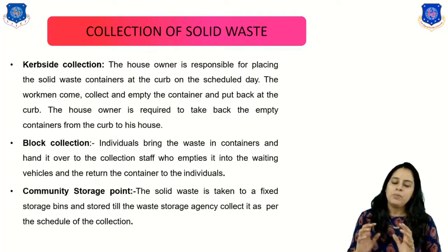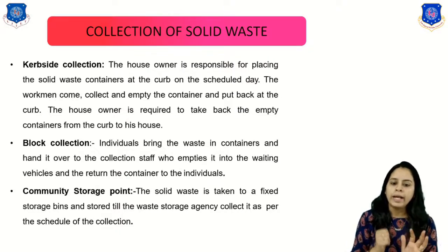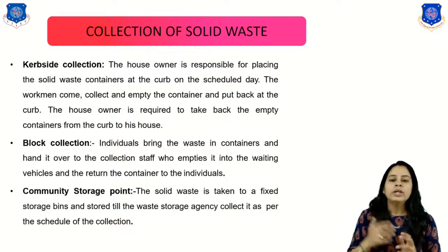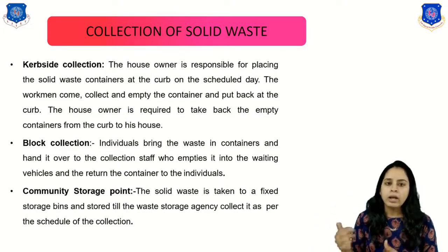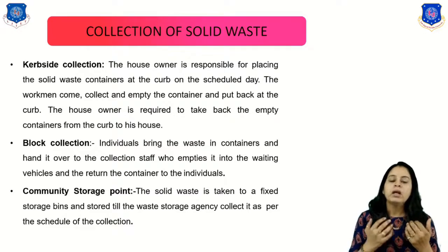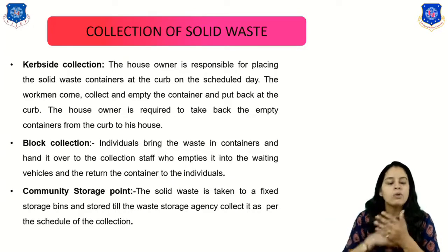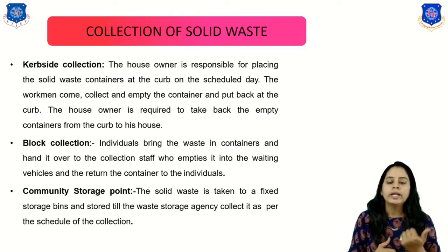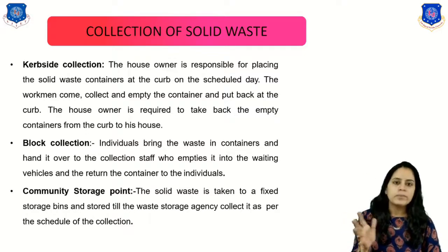In this method, the responsible person is the house owner, who places the dustbin or container at the roadside on the scheduled day, right? The workman comes, collects it, empties the container and puts it back at the same place. The house owner is required to take the empty container back from the curbside to his house, right? So this is the curbside collection.